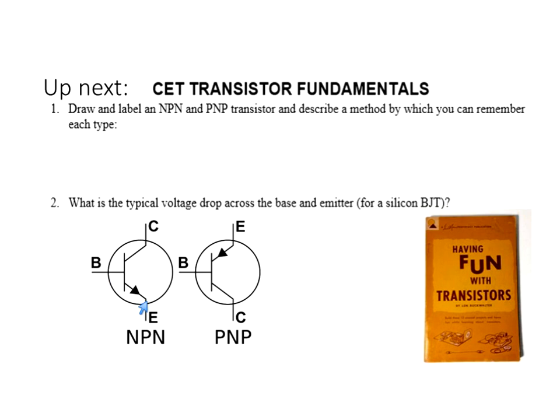between the base and the emitter, if you ever look at the construction of a transistor, how is it built? Well, let's just look at an NPN. You got the collector up here, you got the emitter down here, and you got the base in the middle. And it's actually 2 diodes constructed back to back. Here's your base. And why is it called an NPN? Well, here's N material, here's P material, and here's N material. You have 2 diodes in there. Think about it. Here's the base, here's a diode pointing this way. That's the collector up there. And here's a diode pointing down here. The P material's in the middle. Remember, the P material is the anode. That's the base in this case. The emitter is down here.